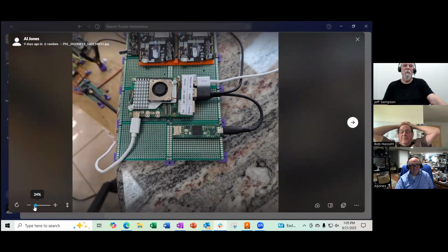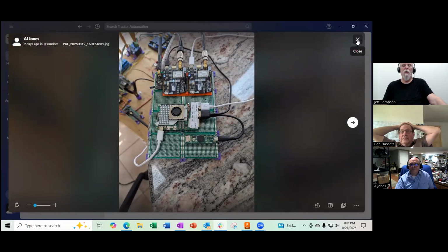On your current setup, when you're running the GPS, you're putting correction data into your moving baseline pair. I assume that's coming in over the USB connector. Is that right? The Raspberry Pi picks it up on Wi-Fi on TCP/IP port 6000, and then pushes it via USB into the BaseLink.